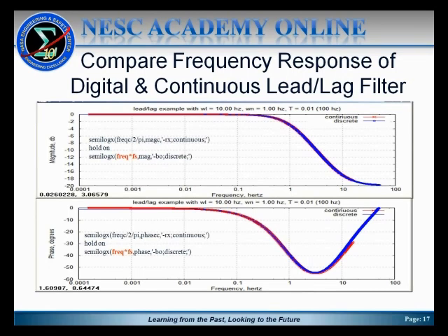And you notice as you start getting out at higher and higher frequencies, approaching the Nyquist frequency, the bottom curve shows a little bit of difference in the phase towards about 15 hertz or so. And that's to be expected, and we'll discuss that a little bit too, of things you can do to preserve some of the frequency characteristics if the region of interest in your filter happens to be getting close to the Nyquist frequency.